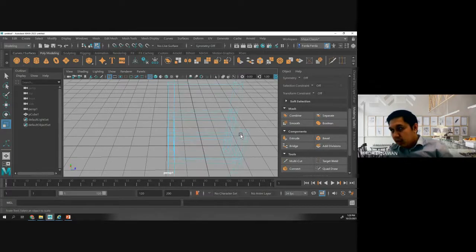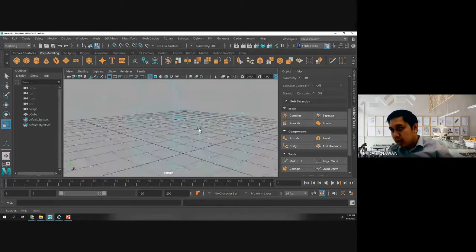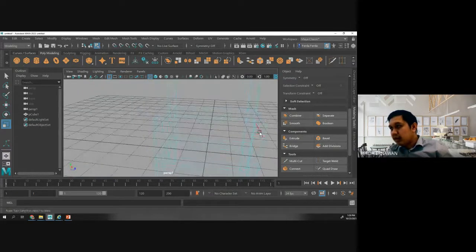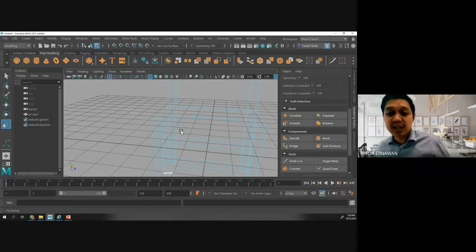If you look at your wireframe here, if there is no wall, you can travel. Let's say you are inside this 3D object, you can travel all this polygon, isn't it? So it means good. This is what we want. When you design, you have to make sure inside there is no wall. Otherwise, you will get an error when you render it. And if you design properly like this, you can easily edit and update it as you want.